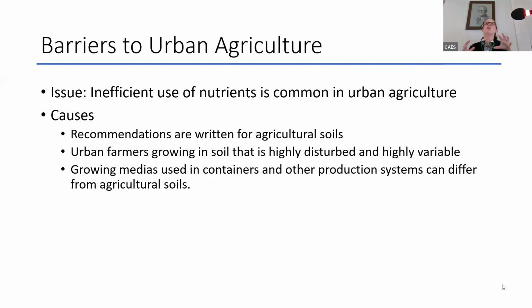In the green roof system itself, temperature fluctuations on the rooftop tend to be a lot lower when there is a green roof present than when there is no roof present. Rooftop temperatures can reach as high as 165 degrees Fahrenheit. But when you put a green roof on there, the evapotranspiration and evaporative cooling that goes on helps to keep those temperatures much more in a comfortable range. That actually helps to prevent heat leaking from the outside environment into the building.